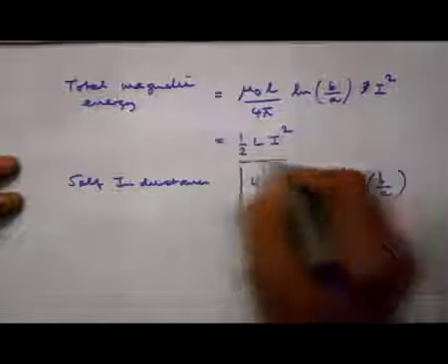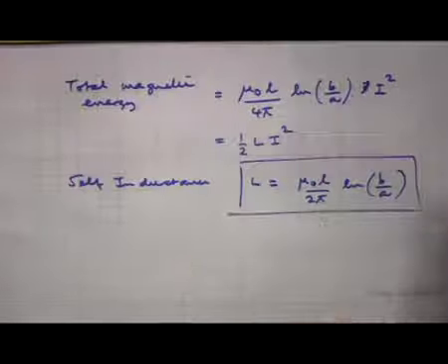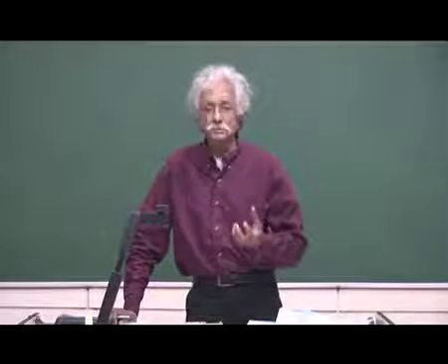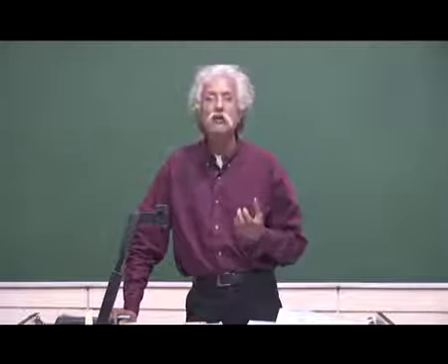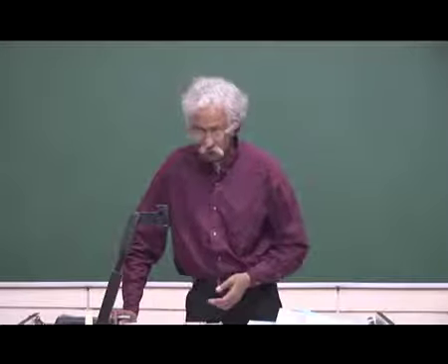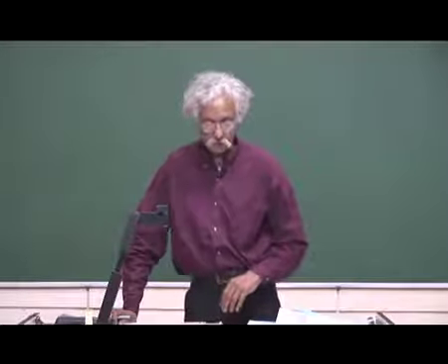So, that is the self inductance of a length L of this coaxial conductor of inner radius A and outer radius B, and the magnetic field that is contained within this pair of conductors stores energy, and that energy is half L I square, where L is the self inductance of this length L of this coaxial pair of conductors.